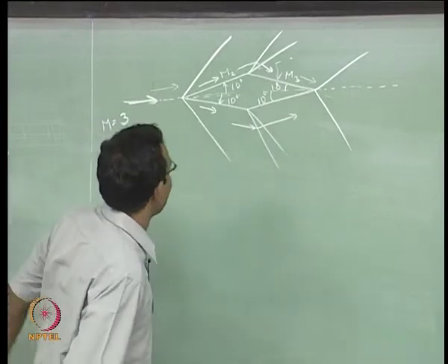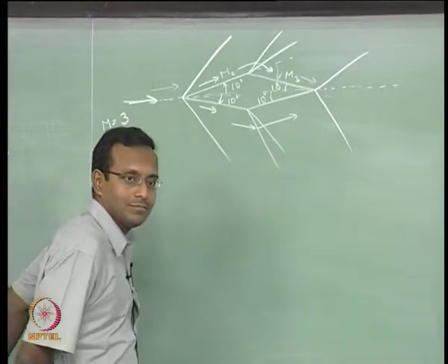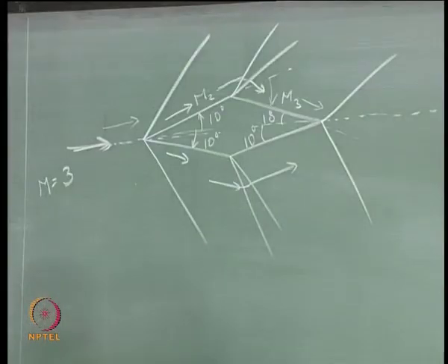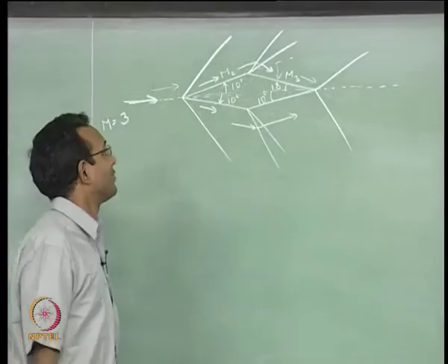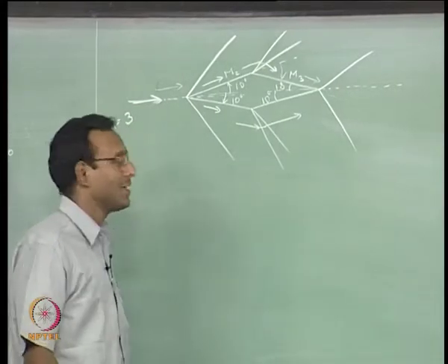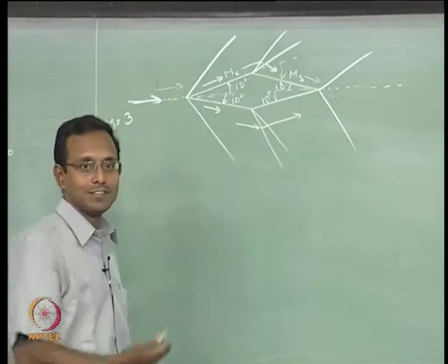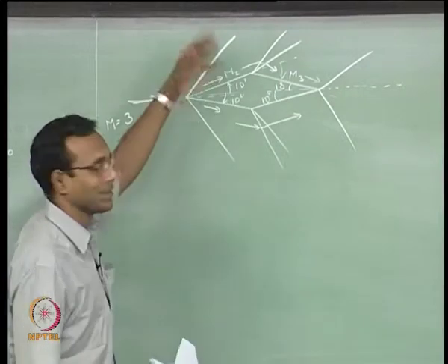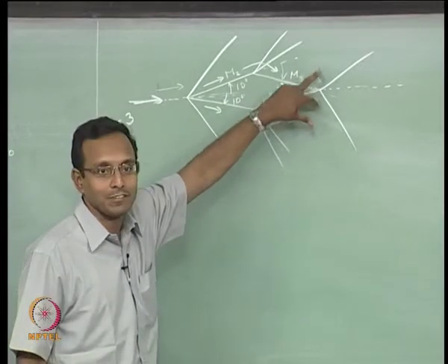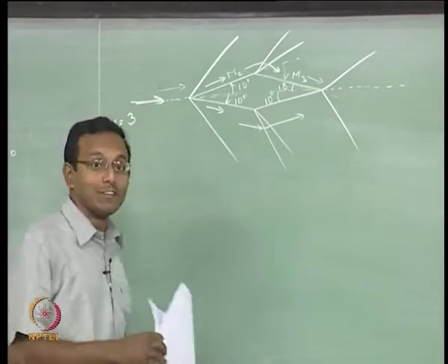Will this airfoil have drag at this angle of attack? Two people say no, one person says yes. So, will it have drag or not? It will have drag. Why? Okay, will it have lift? It will not have lift. Why? It is very symmetric problem. Okay, whatever pressure is here, same pressure here, same pressure is here and here. So, it is equal, there is no lift produced.